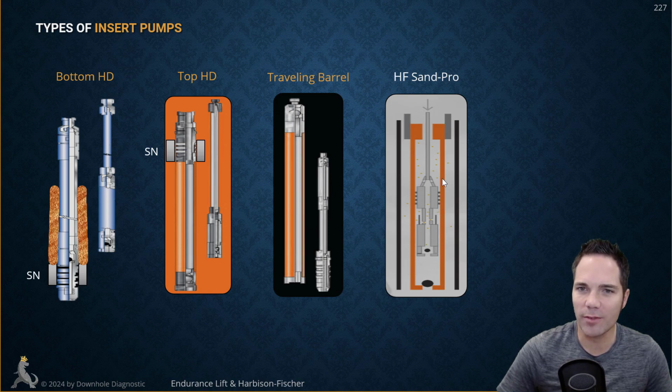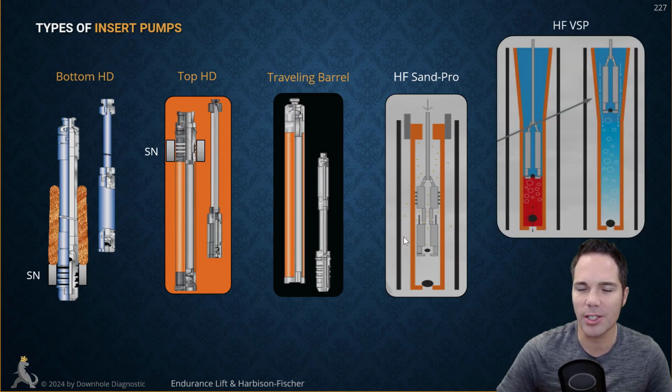There's no pressure differential acting across this plunger because you can see there's some holes right here, so the pressure can equalize around it. So it's not feeling that force that would tend to cause slippage right there. It wipes and tries to keep this plunger in better condition to extend the life of your pump. There's lots of things you can do, with different types of plungers and different configurations.